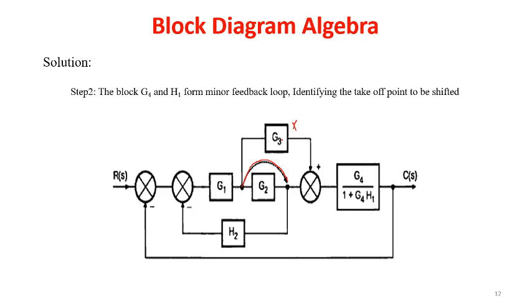So here we have to multiply this particular block in series with the block here in reciprocal, that is 1 divided by G2. So this block has to be brought in series with this particular block, or multiplication of this block with 1 divided by G2, that is this block has to be taken into care.